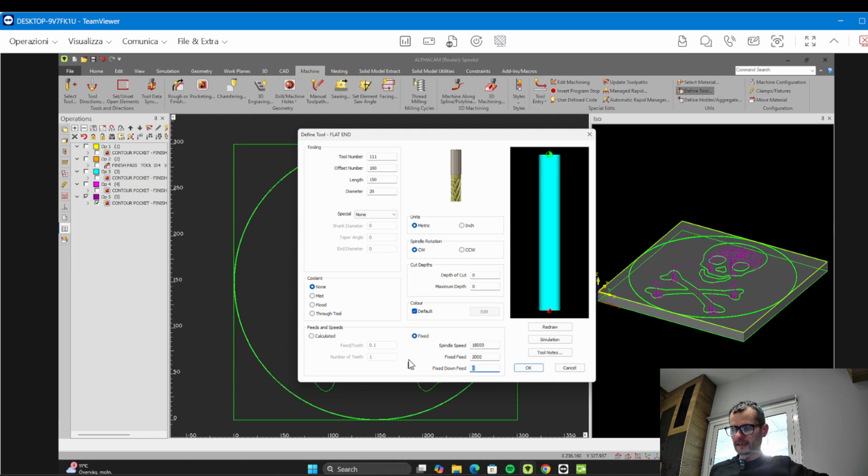And it's like the speed with the ZX. If you write on the machine 0.5, something like this, here you have to write 500. Then the system will make the conversion automatically, so the system will divide automatically by 1000. But remember that when you create something or set a speed in the machine, it works in meters per minute. AlphaCam works in millimeters per minute.